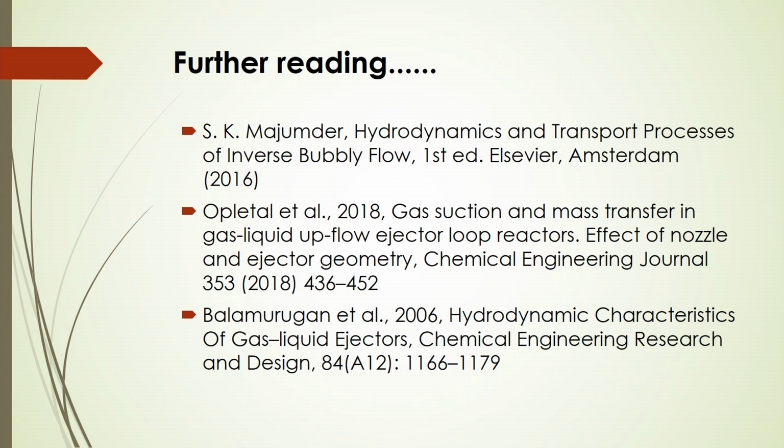So, we have discussed how the ejector can be used for process intensification, for getting more contact between gas and liquid, for more finer bubble formation and more finer droplet formation for chemical engineering operations.